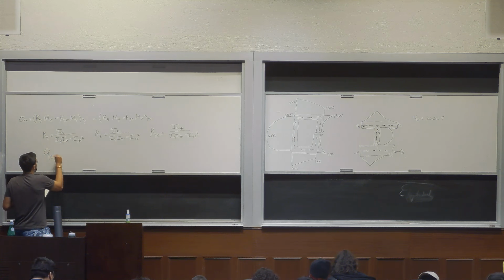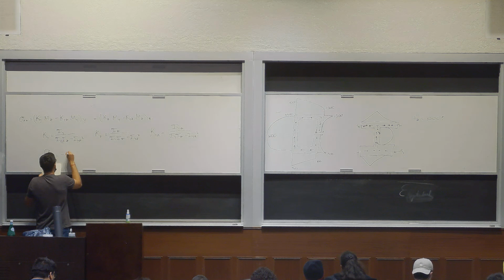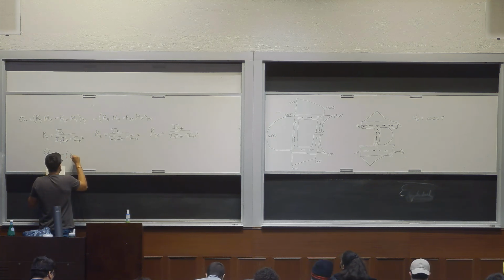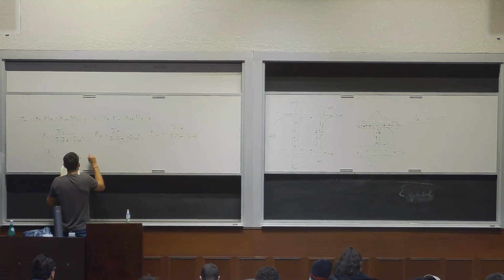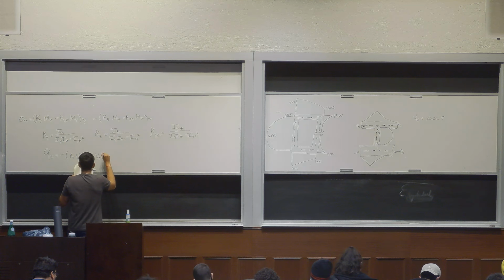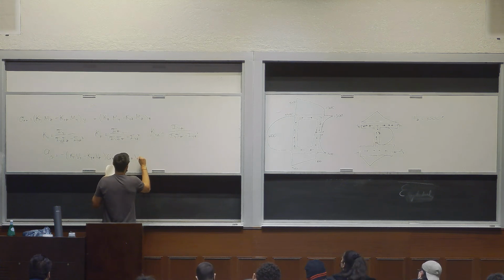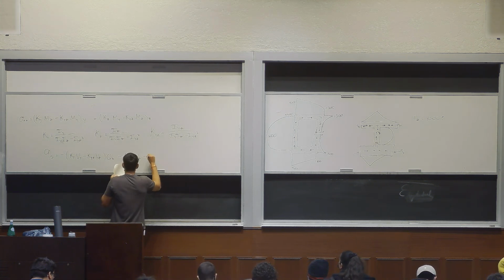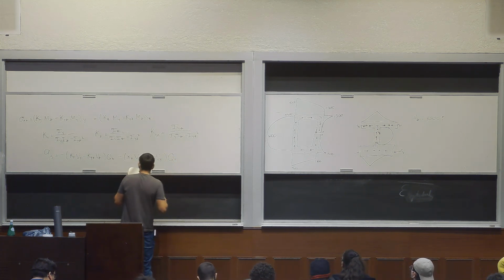So q_s in general is negative (Ky Vy minus Kyz Vz) Qz plus (Kz Vz minus Kyz Vy) Qy.